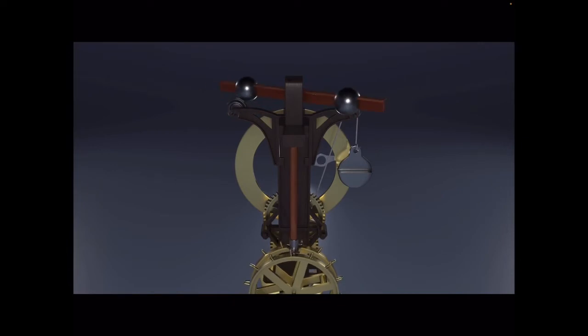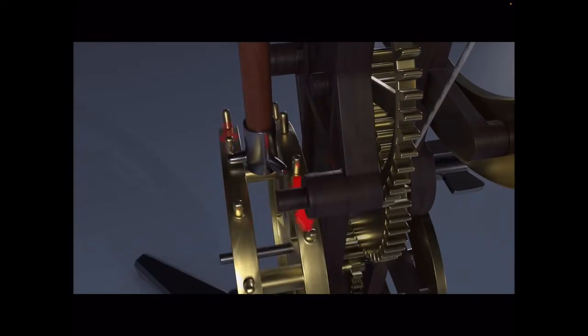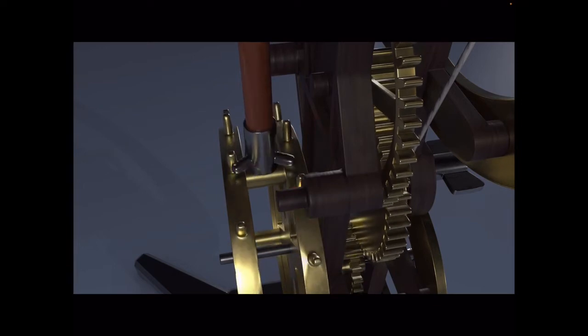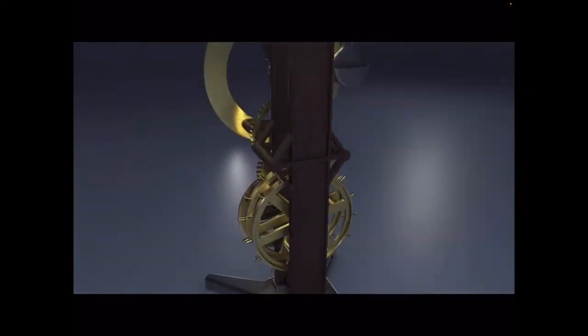The rate at which the escape wheel turns is controlled by the pendulum. The length of the pendulum determines the rate at which the pendulum swings back and forth. The escapement also provides energy to the pendulum to keep it swinging. The escapement must have proper clearance so that the teeth of the escape wheel will advance one at a time, instead of uncontrollably or binding against the pellets and stopping the escapement from swinging.